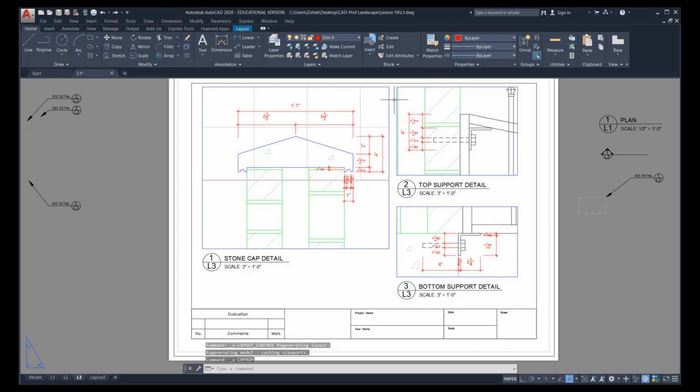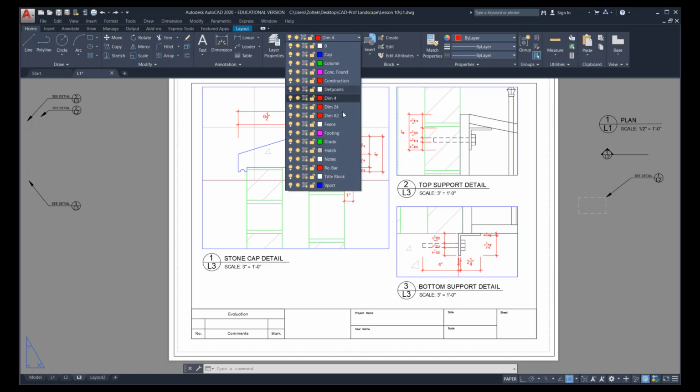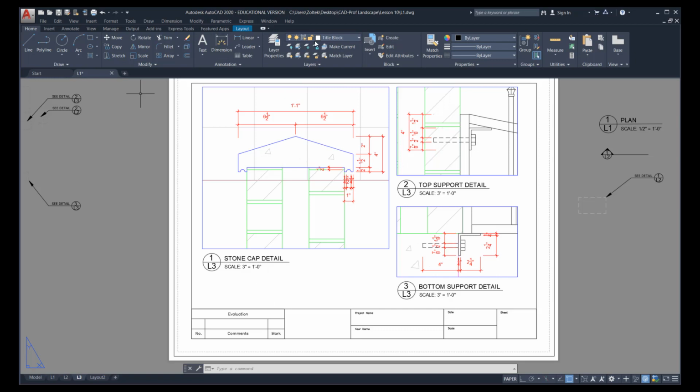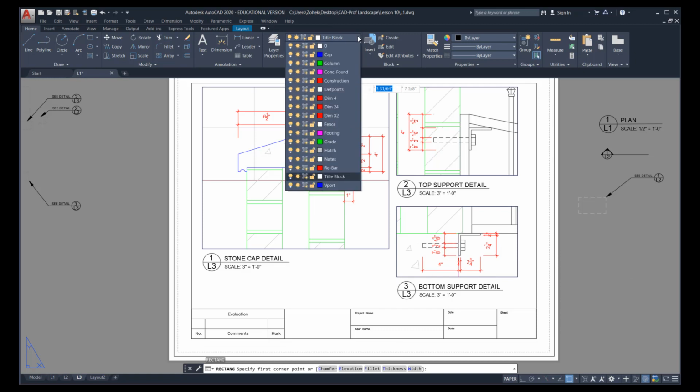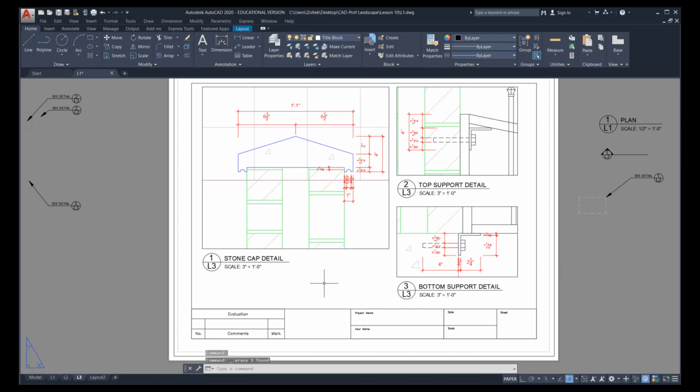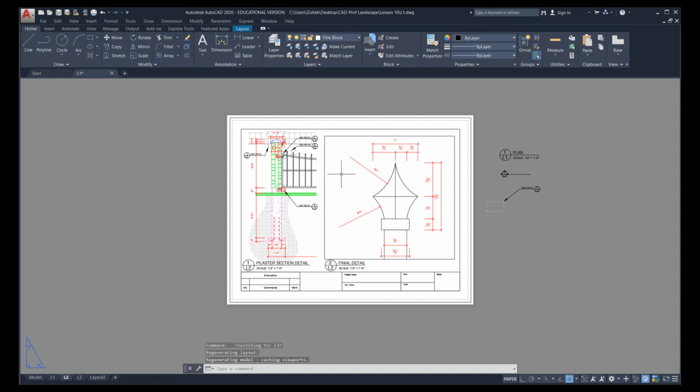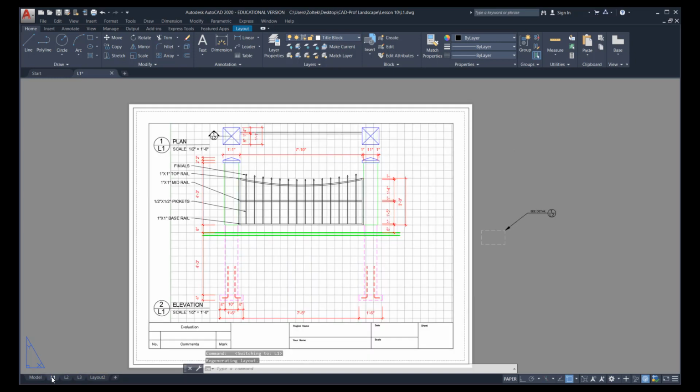Now if I leave these in the viewport and I go to plot this or print this all as a mass published document, I can only have the viewports on or off. I can't have them both. So in order to make sure that they're on in the correct pages, I'm going to create boxes around each of these. So I'm in the title block layer, and I will create a box around each one of these items. So now when I turn off the viewport, they stay on. And when I move to L2, there's my box for the viewport of the finial, where there's no viewport shown here. On the section, there's my L1.